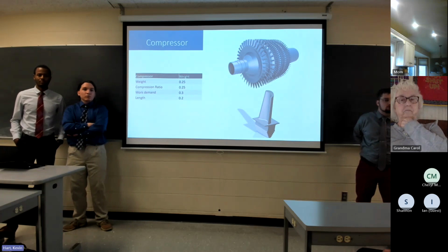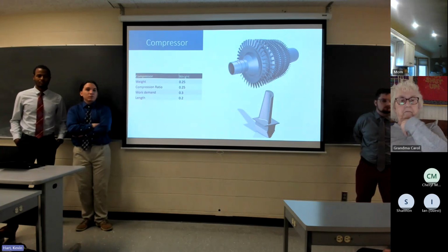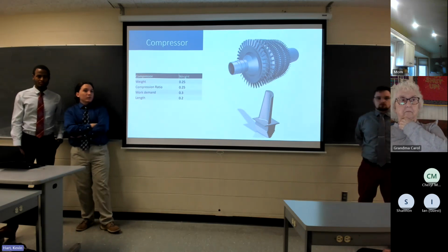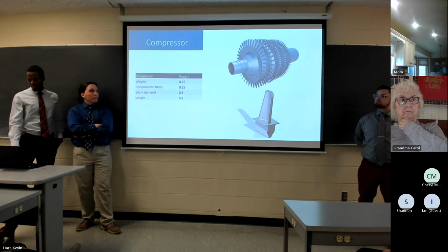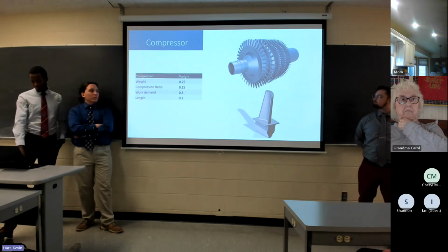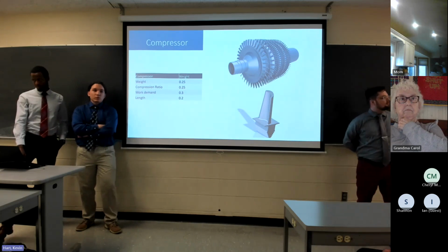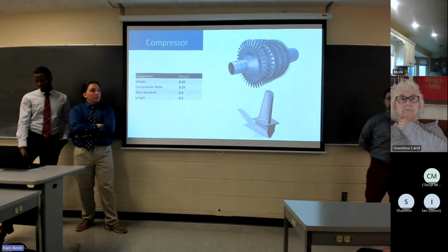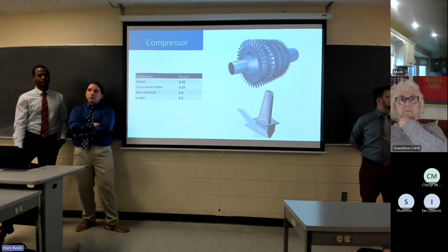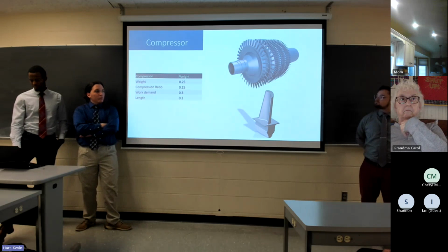What would be a typical number for a typical turbofan in terms of driving the auxiliaries? What percentage of power is diverted to auxiliaries? I believe it's less than about 5%, because a majority of the work is going into compressing the flow through the fan and compressor, and those are very large components, whereas the auxiliaries are much smaller. So I believe it would be about 5%. Okay.